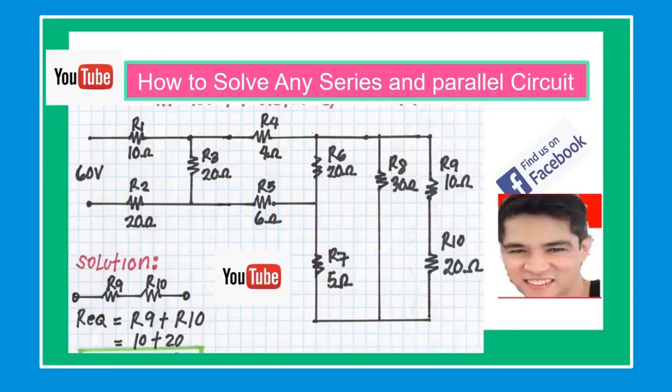Our topic for today is how to solve any series and parallel circuit. In this lesson, we'll first discuss the difference between series and parallel circuits, using the most basic components, resistors and batteries, to show the difference between the two configurations. In a series circuit, the current that flows through each of the components is the same, and the voltage across the circuit is the sum of the individual voltage drops across each component. In a parallel circuit, the voltage across each component is the same, and the total current is the sum of the currents flowing through each component.